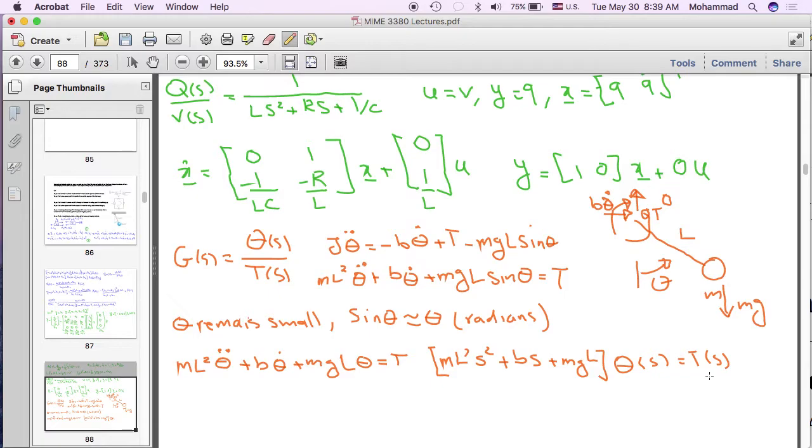Yes, sir. That first equation where you turn J into mL squared, should it be 1/2 mL squared? Is it 1/2 mL squared from the previous solution? Yeah, the last example we did a while back was 1/2. So let's stay consistent. I think you're right. I forgot, and thank you for reminding. So it's mL squared over 2. Thank you. And also here on the very top. Thanks. So mL squared over 2 is the J value for a concentrated mass where the link has no mass.